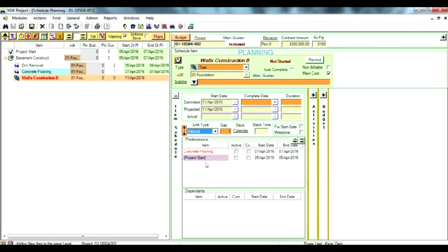So we'll just change that to an interval link type. And we'll use the calendar to set 1 day for a needed gap between these events. Now the start date is recalculated, and the program tells us that the 11th is when we can progress.